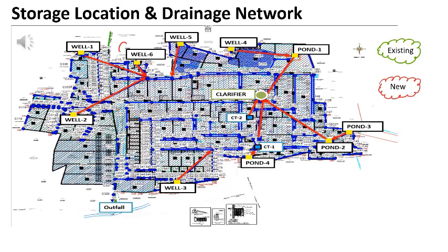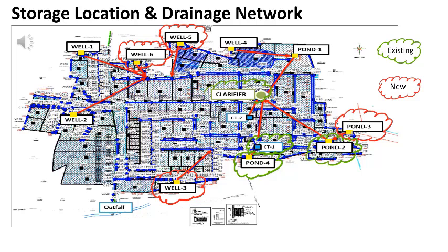Site survey and development of tentative site drawings, division of catchments into sub-catchments, ponds, wells, pumps, drain network, junctions, and parameters related to these components were built into the model. The purpose of the whole exercise was to get optimum pond sizes synchronized with the pump capacities that result in no flooding conditions even in torrential rain situations. Another design objective was to enable the drains' self-cleaning velocities. This was done in the due process.